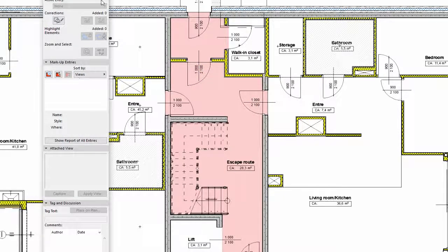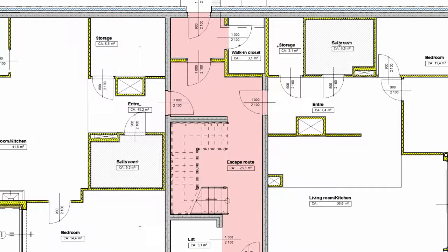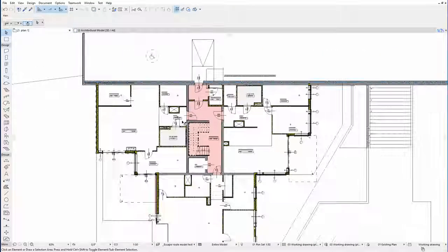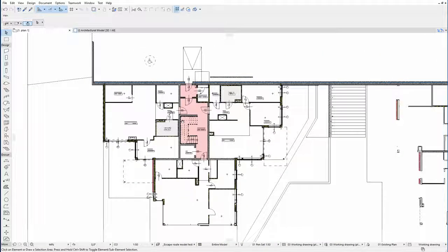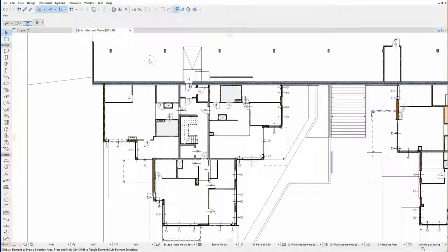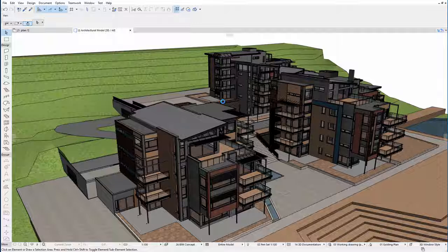We can create BCF files using ARCHICAD's markup tools. With the evolution of BIM as the de facto workflow, architects increasingly receive consultant information in a BIM format. To help architects fulfill their role as lead coordinator, ARCHICAD's collision detection allows 2 groups of elements to be compared through user-defined criteria sets. These criteria sets can include element types, classification values, property values and attributes, such as layer names or building materials.